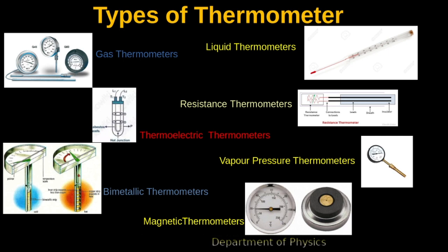The constant pressure gas thermometer. This class of thermometers can operate at both constant volume and constant pressure. Having a very precise measurement system, they are often used to adjust other thermometers. In this thermometer, volume increases directly with increase in temperature. It measures the temperature in the range of 0 Kelvin to 500 Kelvin. In the other type, pressure increases directly with the increase in temperature.